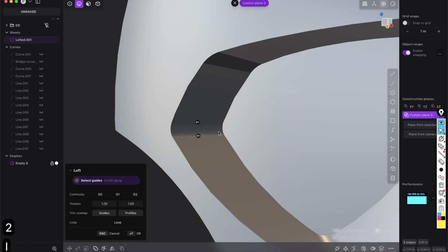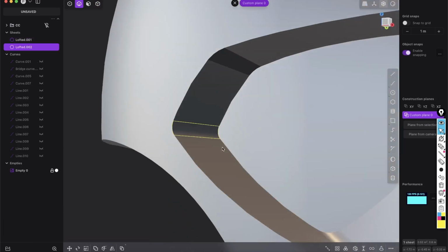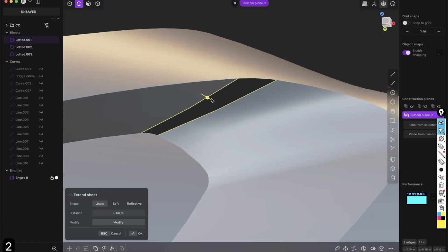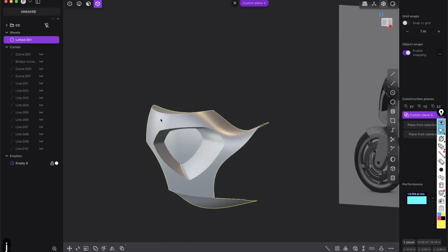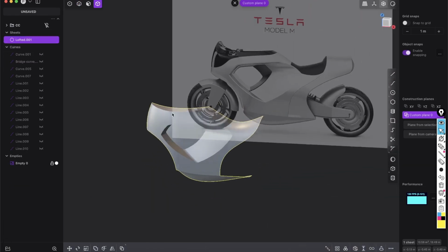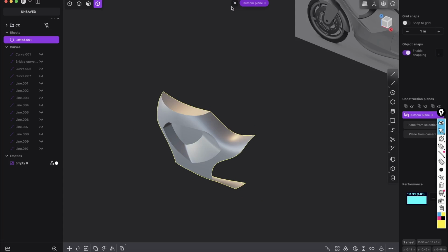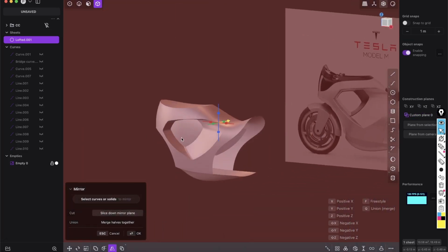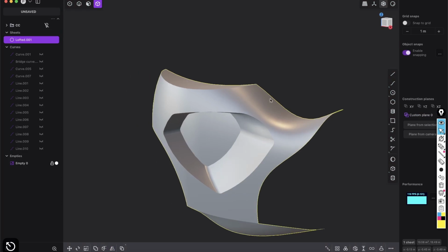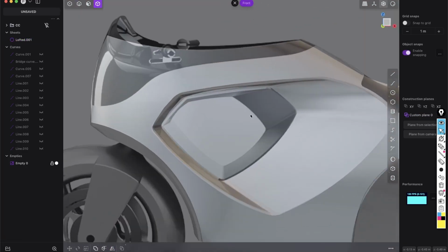So let's do those ones here as well. Those look pretty good because you see it's very simple. And here again. And once you have that, press 4 again. You are in object mode. Select all the surfaces and join. So you just have one nice surface. And if we bring it here to the other side, you see we get really cool result here. And let's continue